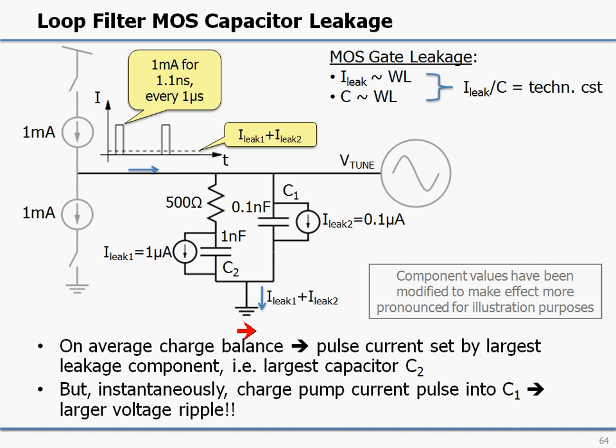Of course, to maintain a steady state in this system, the charge pump is going to have to inject the necessary charge to replenish these capacitors, but the charge pump can only do this with very short pulse type signals. But on average, they will compensate the leakage current that droops away over here.